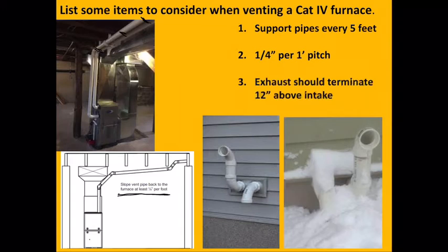And of course, the exhaust pipe should terminate 12 inches above the intake. What I'm referring to is the separation between this pipe and this pipe.